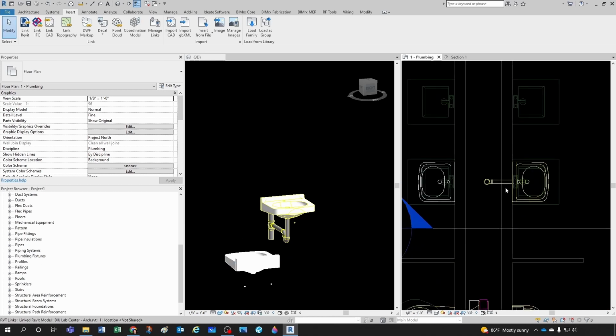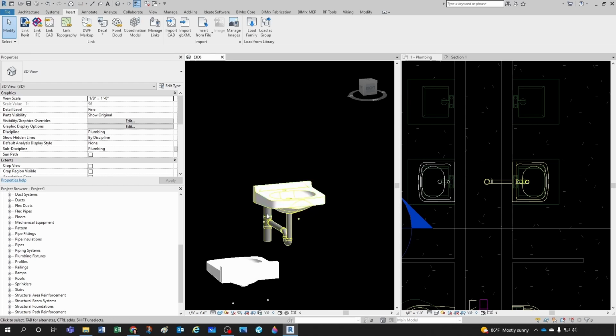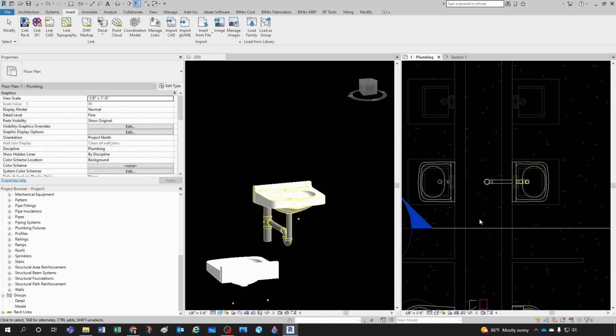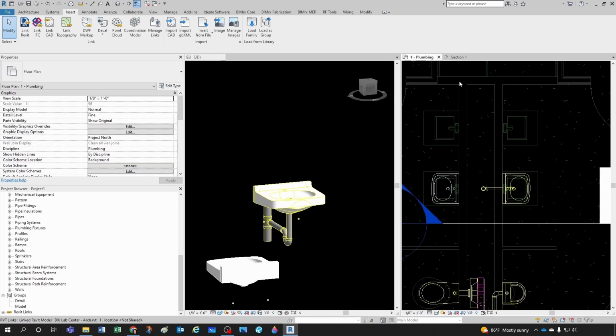And what I typically do is I would have this lavatory completely piped with sanitary drainage, cold water, hot water, and make it a group. And I show you how to do that in another video. You can check it out. The link's going to be in the description. Then you will have it available here under group. See, under model, you would have a model detail that's called wall mounted lavatory fully piped. And you can simply drag and drop from here to here, and you will have everything ready to go, including the P-trap and even the stack. You can have back to back as a group and just drop it here. Okay, I'm just showing you from scratch so you get the worst case scenario.